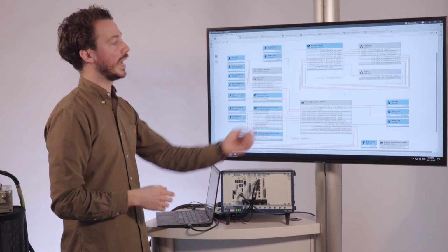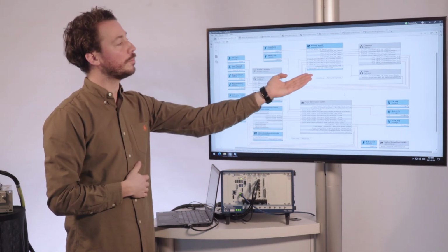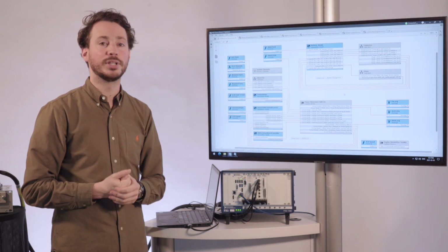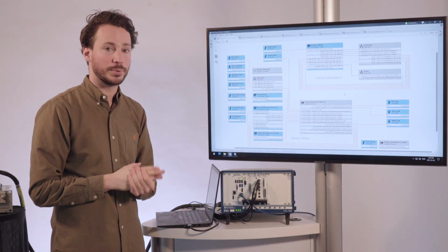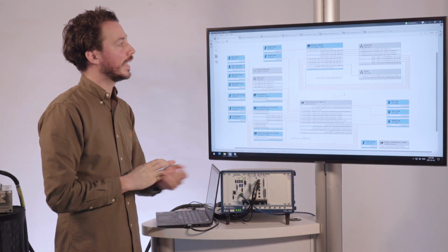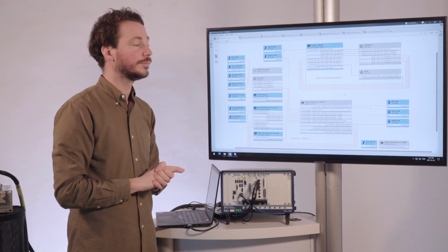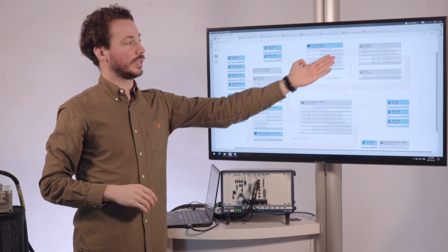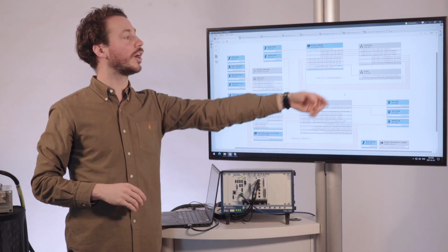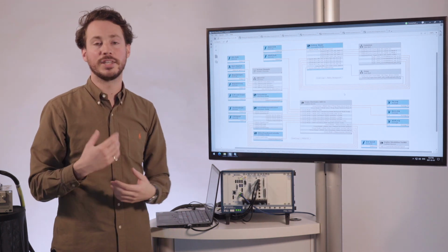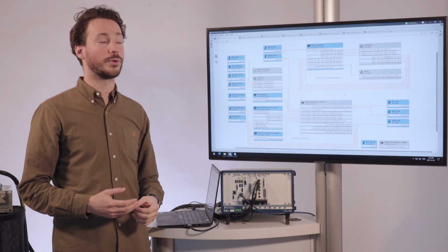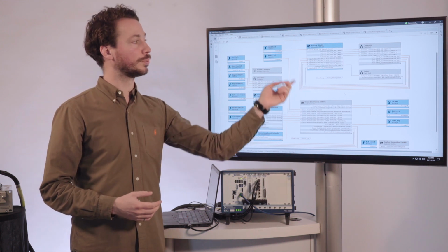And last but not least, we have the battery model. So the battery model is, like I mentioned, a Simulink model using the SimScape toolbox from the Mathworks. And it is simulating in the real-time controller a very detailed battery model to then connect to the Comemso hardware, and then from the Comemso hardware, that's connected to the ORION, and the ORION will perform the cell balancing that we saw before. And that's another loop.